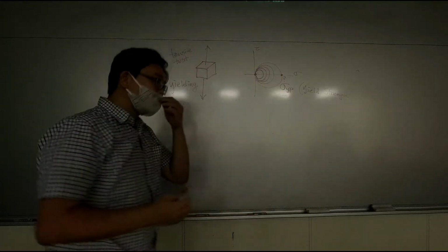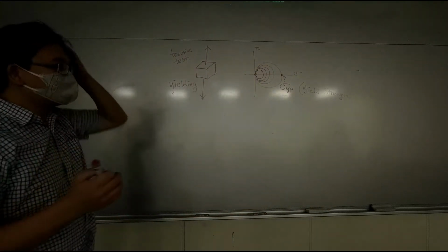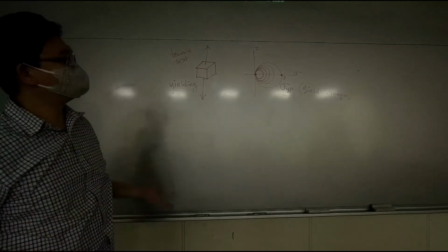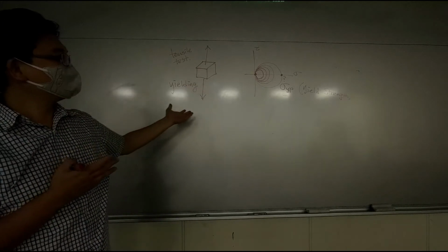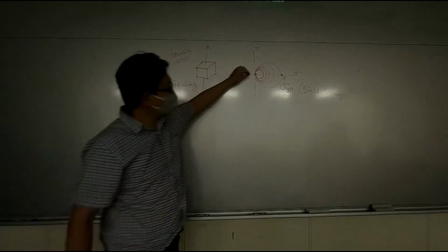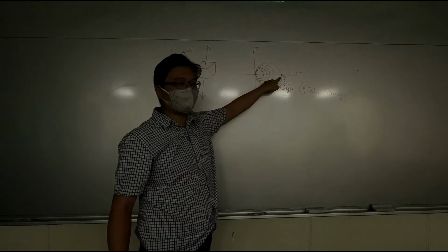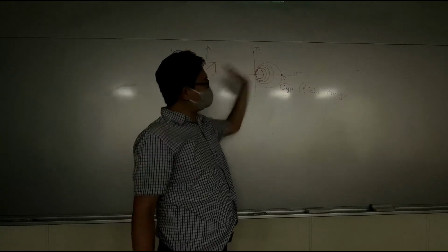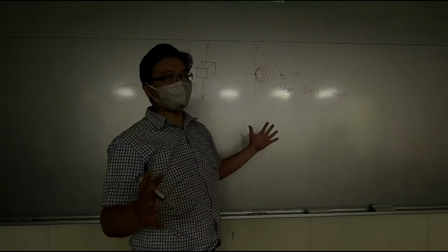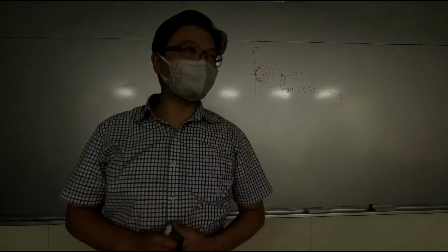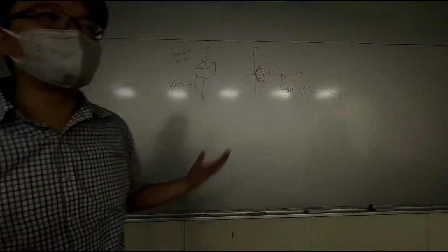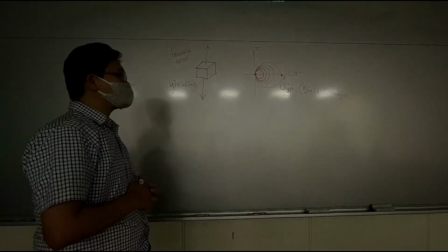Okay, so for metal, it's always like this. Tensile test, and then you enlarge the Mohr circle until you reach this point. Then, whenever it's above, the material is no longer good for us because it deforms permanently.